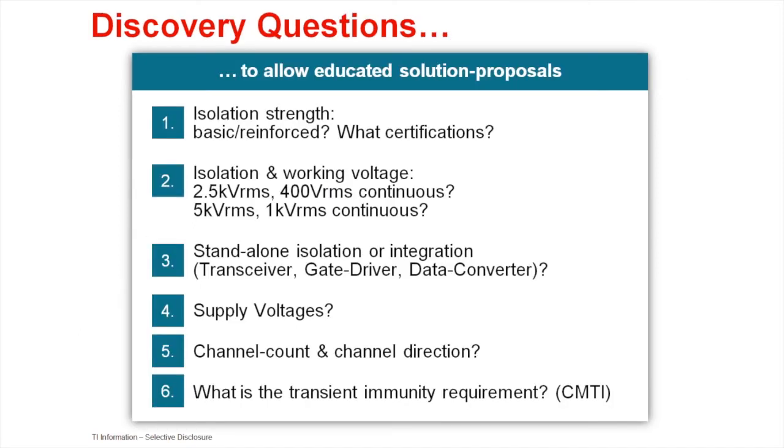Lastly, we can show you some discovery questions. These are questions to think of when designing any isolation system. What level of isolation is necessary? Is it basic and functional, or is it reinforced? What are the certifications that you're designing to? What level of isolation do you need for VISO or for working voltage VIORM? Do you need just a standalone digital isolator, or would you need an isolated function device, such as an isolated RS-485, isolated CAN, isolated gate driver, or even an isolated data converter?